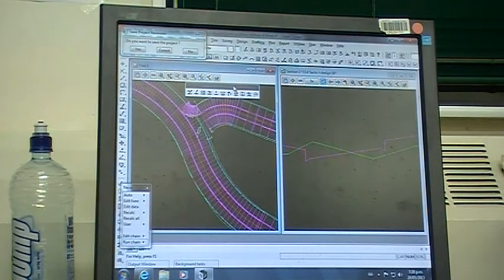You can use it to calculate pre-development runoff flows and intensities and peaks as opposed to post-development, so that you can prove that you're not harming the environment, that your design eventually will either keep the runoff in the same state or better than it was. Okay, we can design detention systems, basins, dam walls, levels of orifices, all that kind of stuff. Okay, the longer you use it, and some of you will get to go off to consultants and get pretty good at it. It's really quite amazing stuff.